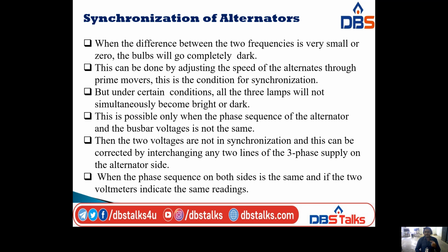This can be done by adjusting the speed of the alternator through the prime mover. This is the condition for synchronization. The prime mover is used to drive the alternator at synchronous, or constant, speed.